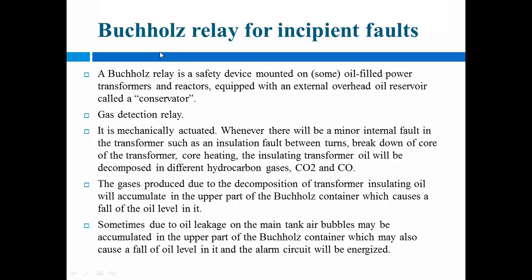These accumulate in the upper part of the Buchholz container and cause the oil level to fall. The reduced oil level again increases the heat, and your relay will actuate.